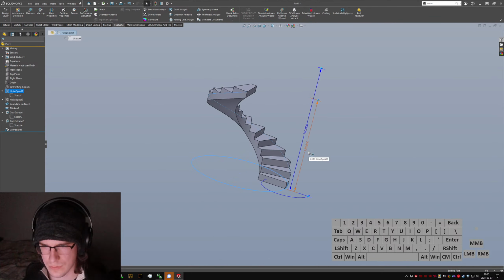Let's see what the pitch is going to be. Constant pitch. Can I do pitch and revolution? Pitch is 160, revolutions 1.25. Yeah, that's not bad. I have to make that match the pitch exactly, but that's not too difficult. And I think we can even do that with a quick equation applied to this curve pattern.